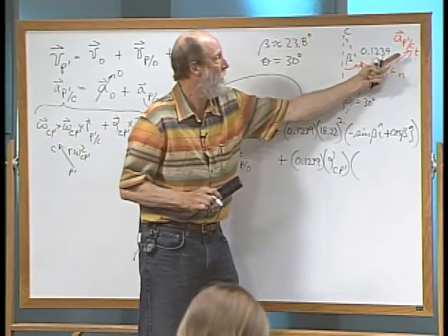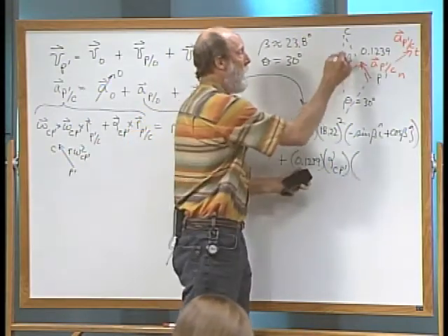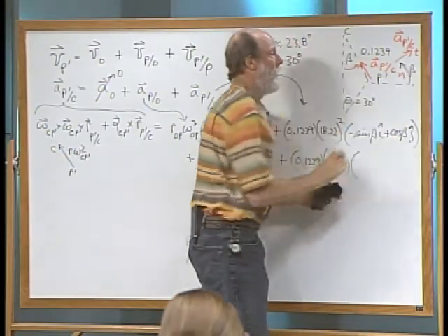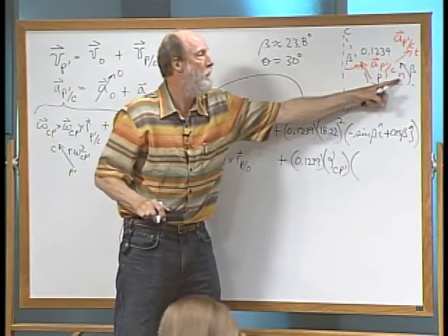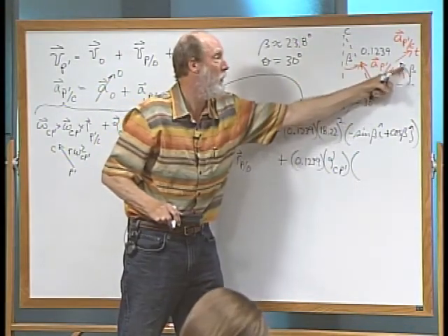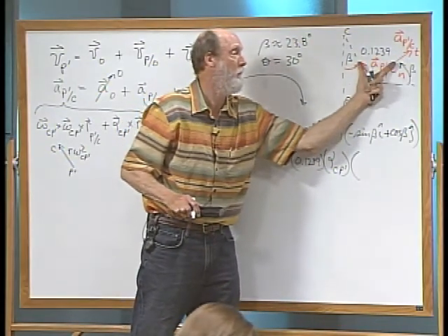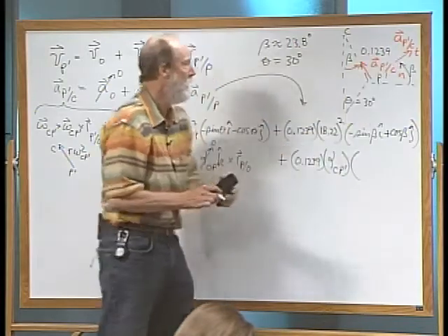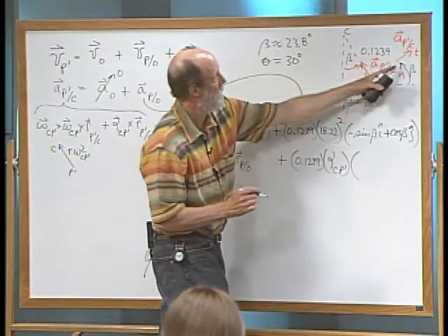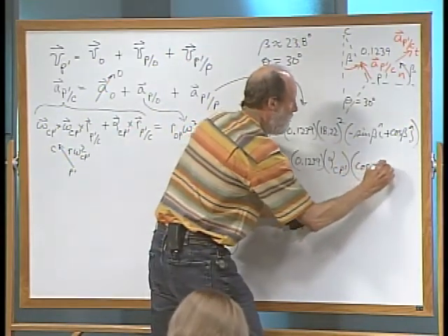So that's going to have a reversal, a positive, positive, isn't it? And so if this is beta off a vertical, then that means this is beta off of a horizontal. Beta off the vertical becomes beta off the horizontal for the orthogonal acceleration vector. So you can look at that really easily and see that you're going to tag a unit vector on there with a cosine beta i plus a sine beta j.